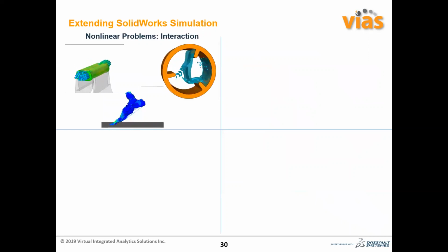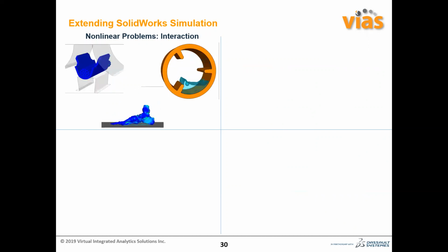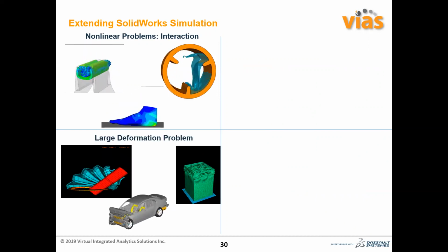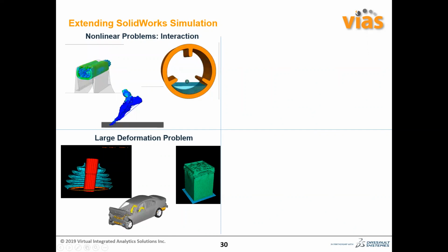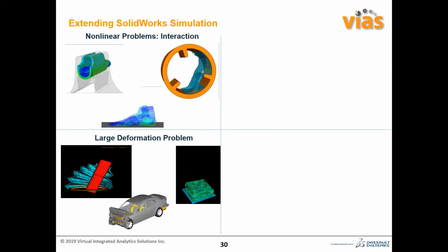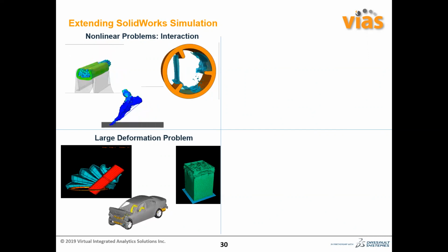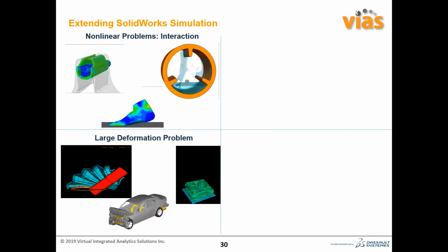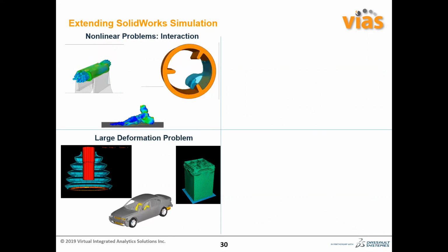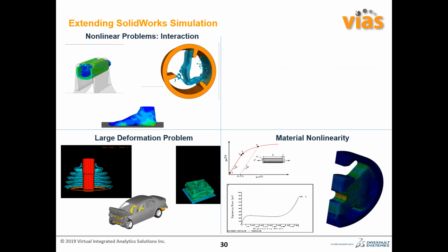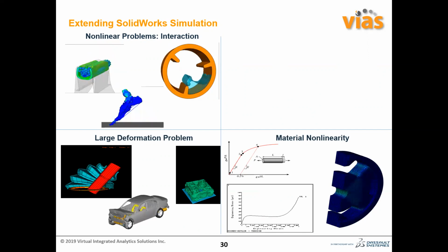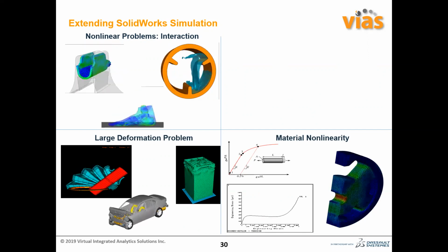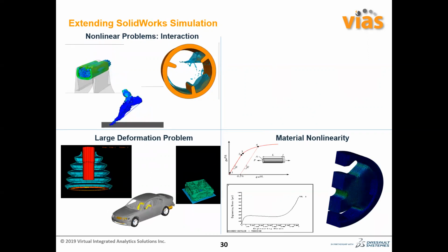Every nonlinear analysis tool has its own limit on the amount of complexity it can successfully resolve. SOLIDWORKS Simulation Premium starts to reach its limits as we include several no-penetration contact interactions in a nonlinear analysis. SOLIDWORKS Simulation Premium users are already familiar with the occasional warning message indicating that the software is struggling with convergence at each step. Simulia Abaqus has a more robust contact solver, which allows us to resolve these contact interactions more effectively, and has richer control over some of the contact interaction options. Also, there are usability differences in this situation.